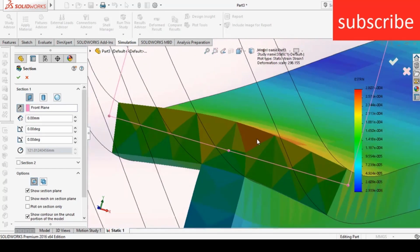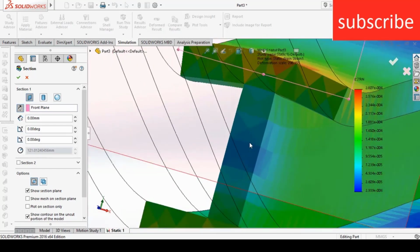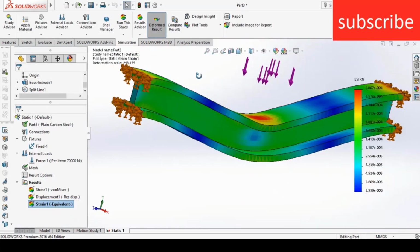Here you see the triangles. So basically these are the nodes that I told you. They are basically the mesh size. Because of the mesh size, these triangles are showing. If you want to reduce their size, just reduce the size of your mesh, and you will get a much better result from here on.